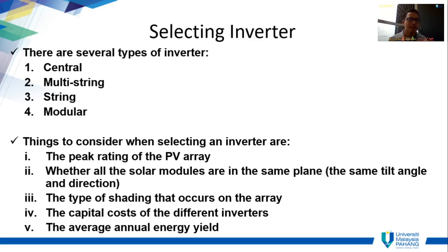Okay. So next is the capital cost of the different inverters. Of course, you need to do market surveys for all the inverters available online, or ask the distributors and suppliers, and then do a survey first. Go through all the specifications, the price and the size, and get the rated power. It should be suited to your system.